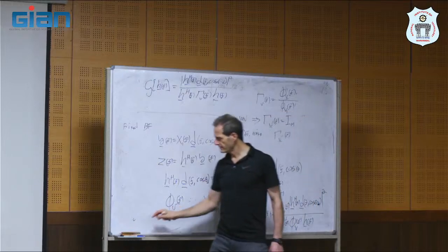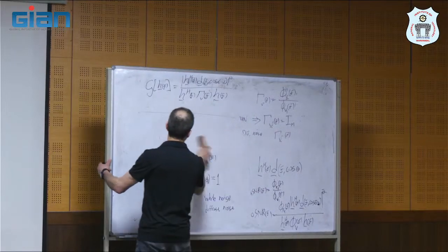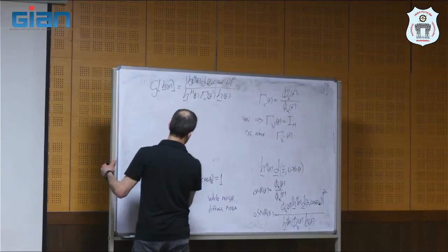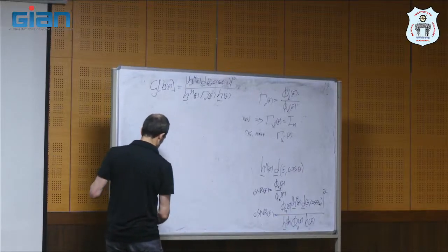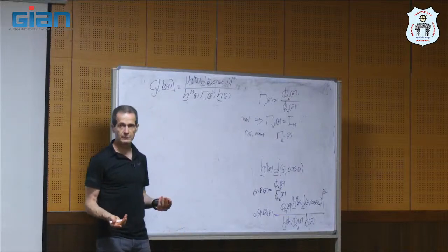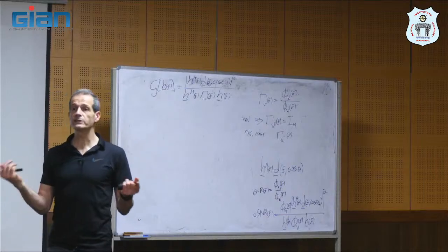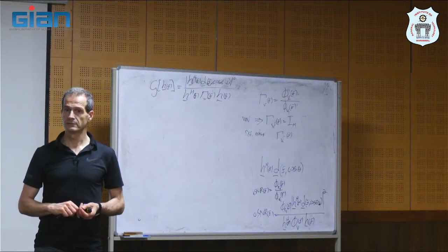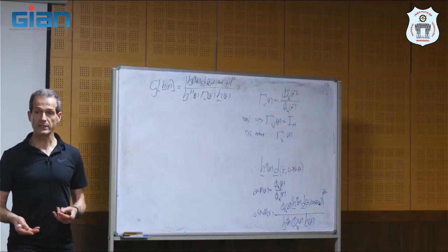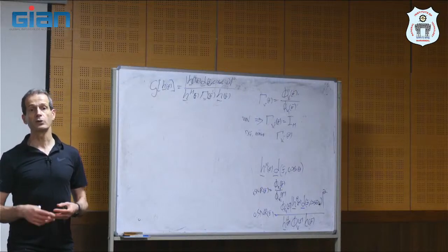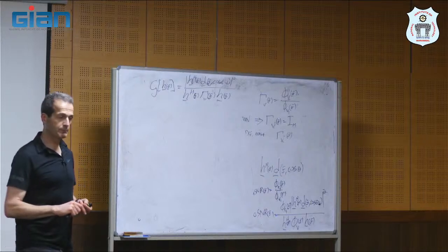So we can find a beamformer that maximizes the SNR, assuming that the noise is spatially white. Or we can find a beamformer that maximizes the signal-to-noise ratio, assuming that the noise is diffuse. Or we can take a combination. Okay? So these are the performance measures.